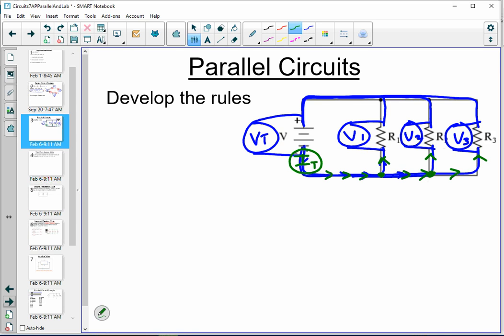One of the key elements is after passing each of the circuit elements, all of the current meets back up on the top and joins together. So if we were to measure the current up on the top branch, we would also be measuring the total current once again up there. It's because current doesn't get used up in a circuit.